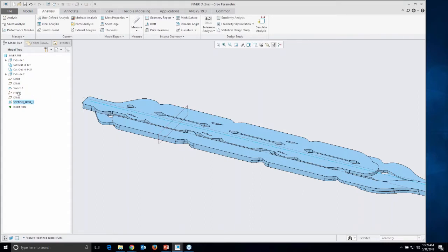And then we're going to go ahead and group these. And now we can click on user-defined analysis. Okay, so a UDA has a field point that it starts with. It has some stuff in the middle, doesn't matter what it could be, but then it ends with a feature, a behavioral modeling feature.